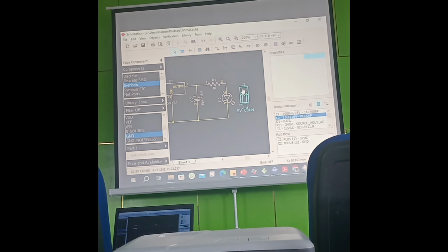This is the connector, right? These two connectors, one of them is supposed to connect to 5 volts. What's the name of the net? 5 volts. You can see it's showing 5 volts. The second net is ground. You can choose any one. There's no polarity for that.